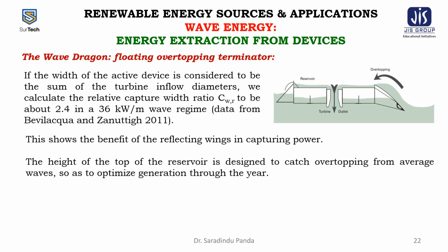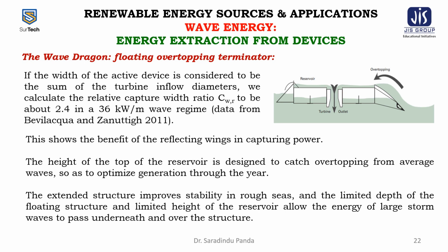The height of the top of the reservoir is designed to catch the overtopping from the average waves so as to optimize the generation through the year. The extended structure improves stability in rough seas, and the limited depth of the floating structure and limited height of the reservoir allow the energy of the large storm waves to pass underneath and over the storm.